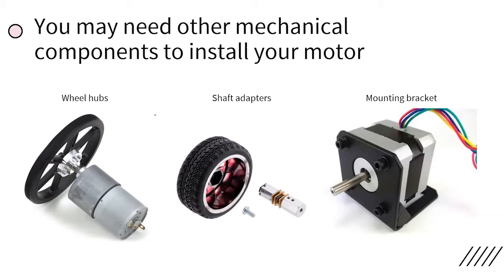You also have to consider how exactly you're going to be mounting your motors into your system. In many cases, like stepper motors, you're able to buy standard mounting brackets that you can already use. But for some instances, like what we find at RAS with SumoBot, we will often 3D print our own motor brackets and build them directly into the system. So it's important to consider that as well when you're deciding on what motor you're going to be purchasing.